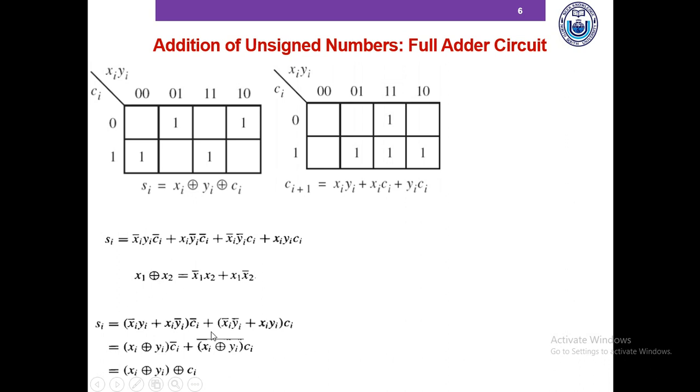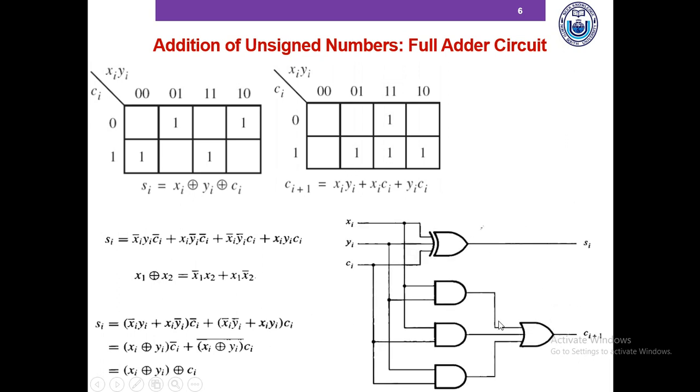So hopefully you don't have any problem with this derivation, and we cannot further convert it into another logic gate for the carry, so we can just go on and implement this in a logic circuit. So this is basically the circuit of a 1-bit full adder. This, unlike the half adder, also considers the carry from the last sum operation.